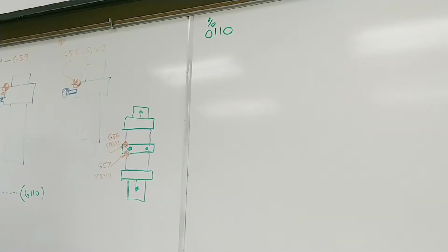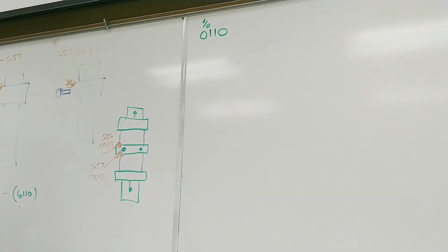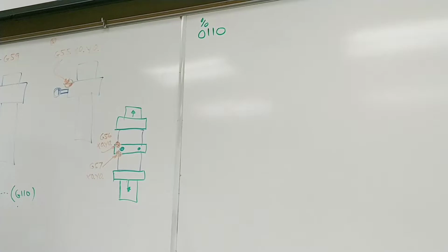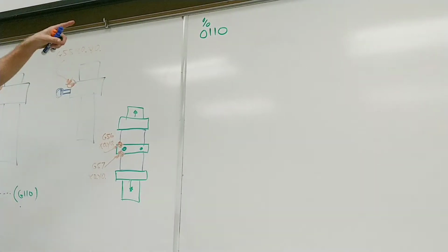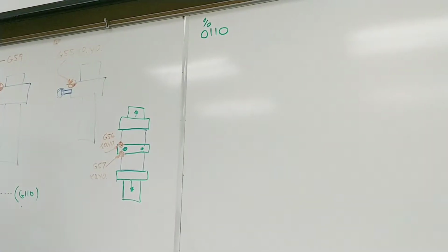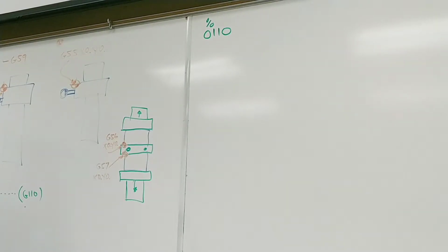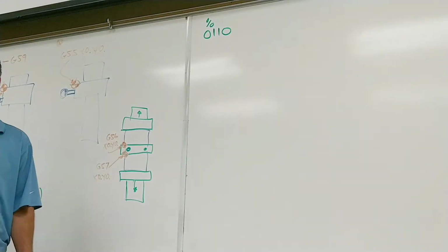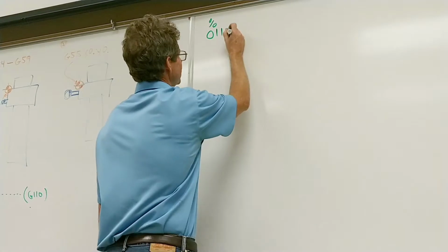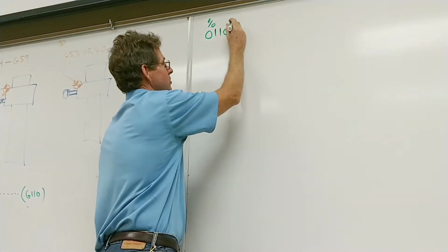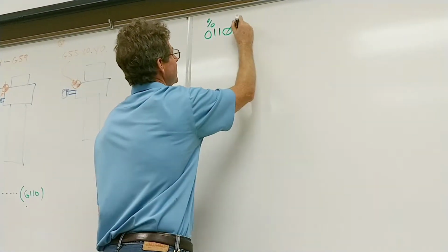And is there actual differentiation between 0 and O? Yes, there is. Okay. Yep. Try to put a 0 there, and you will alarm out. Because that's how it stores. Yeah, that's how it stores it in the program library. It looks for that O, looks for the number, and that's how it stores it. And all Fanuc and all Haas machines will do this. Okay? So that has to be an O. It looks the same, but that has to be an O.